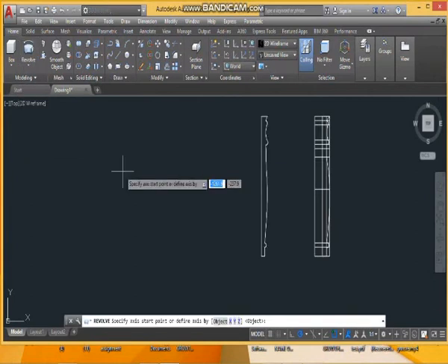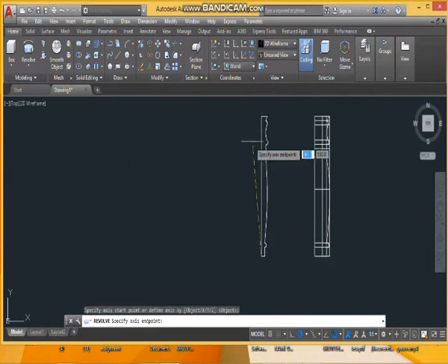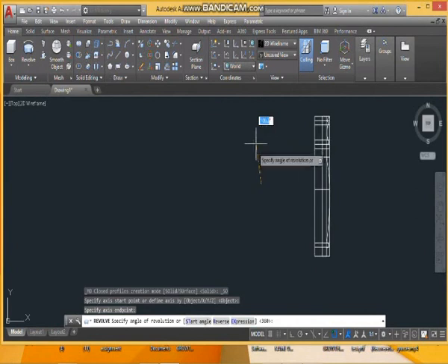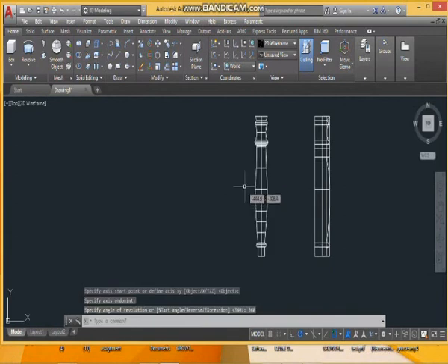Alright, now we are going to, as usual, under the extrusion tool, click on the revolution tool. After highlighting what we want to rotate, we select the axis of rotation. Obviously it is a vertical axis, and we click and type 360, which gives us the complete revolution. And what do we have?